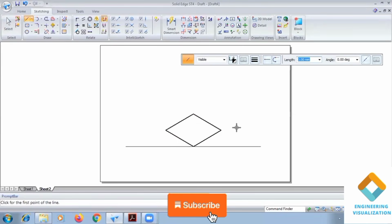Now for the vertical height, we need to give a height of 50 mm. One line I will draw, length of 50 mm. Then go to the move command, create a copy of it, or you can directly do it like this. Then 50 directly we can do. Angle is 90 degrees. Now construct the top face. So the cube construction is done, guys. The cube we have constructed.